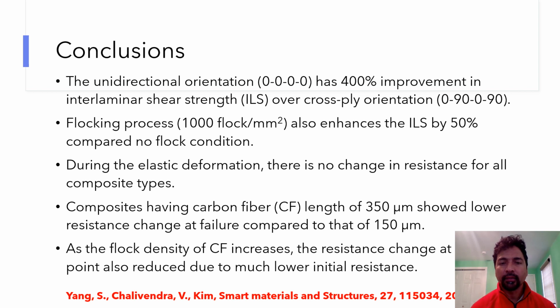Also, the flock density of carbon fibers increases the resistance change. As the flock density of carbon fiber increases, the resistance change increases, yet at 2000 flock density, the change at the failure point is very small compared to other systems due to much lower initial resistance.